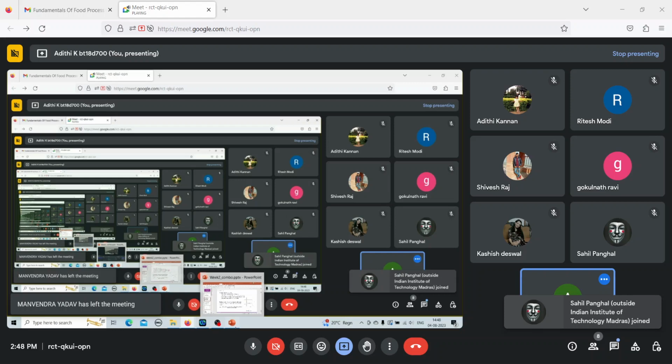If the relaxation time of the liquid is less than the characteristic deformation time, which is basically the total time of observation. So your Deborah's number is basically relaxation time of the liquid divided by the characteristic deformation time or time of observation. So if this is less than the characteristic deformation time, then it means that Deborah's number is less than 1. That is, if numerator is less than the denominator, your Deborah's number is less than 1.